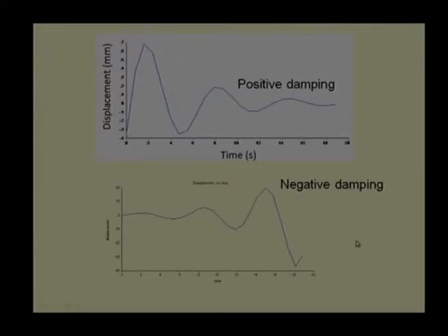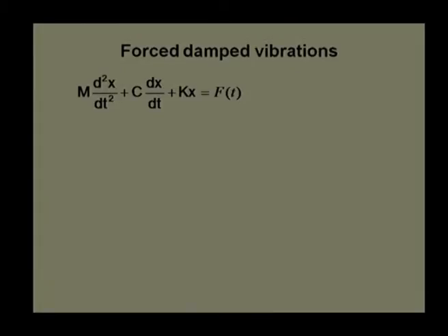If you say a cast iron shaft and cast iron block are there, and we are using some ceramic component against the cast iron, and we experience negative damping, naturally the cast iron will break, or the ceramic block will break, because they have low fracture toughness, and failure will occur. So that is why we should avoid this kind of negative damping as far as possible, otherwise we need to redesign the system so that this can be avoided.